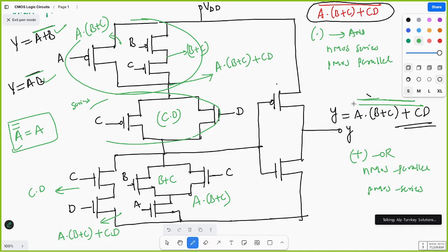So this one I implemented. This is nothing but this circuit. Again an inverter is there, no? So this inverter I need to implement. Okay, with one more inverter, you will get this function. Did you understand? Any doubt? Okay, shall I move forward? So like this, you can find out any Boolean expressions, and you can implement any Boolean functions also.